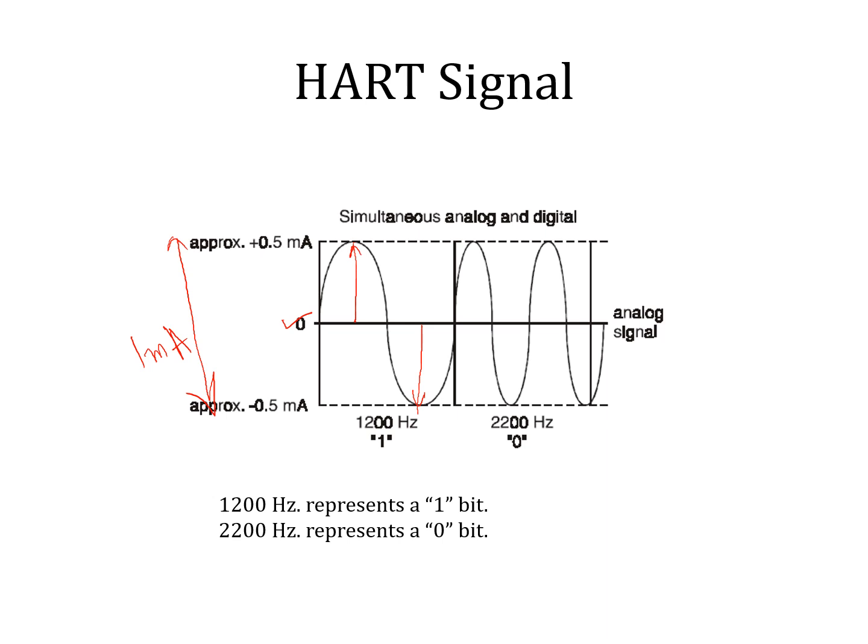For low frequency, that is 1200 Hertz, the logic is 1, and for the higher frequency, that is 2.2 kilohertz, the logic is 0. So two different frequencies have been used to represent 0 bit and 1 bit. So that is why we call it as frequency shift key